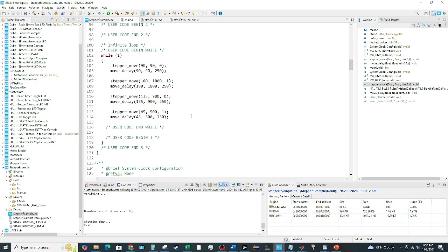So there's a lot of things to think of when you think about what your actual application is going to be. Also, the slowest you want to move could be an impact too, because that period is going to have a maximum value determined by 16 or 32 bits, which is actually a pretty large number, but that's going to also be the slowest you can issue pulses. So you're not usually going to be limited on that end, but it's something you need to think about. Your prescaler could impact that as well. So you need to think of a reasonable prescale value that'll give you values within the window of what you intend to operate.